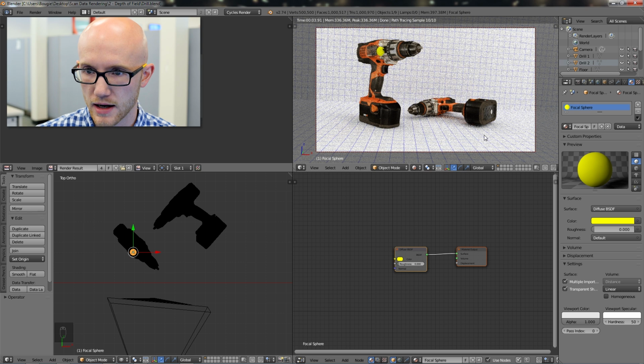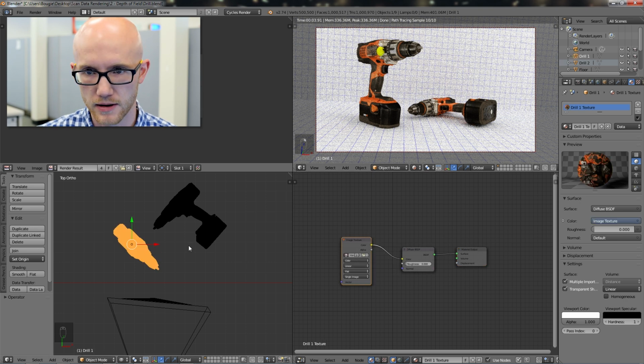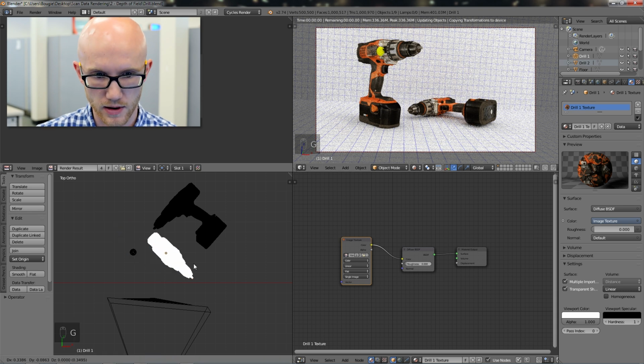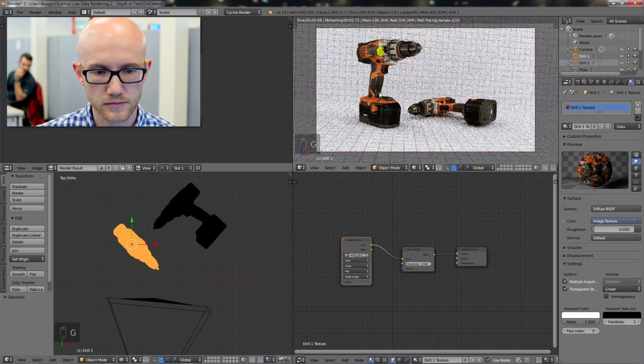And then this time, I've got my two models. I have textured planes. I added a grid that I created in Adobe Illustrator, and then exported it and tiled it to make it look real nice, give it kind of that mechanical grid type look. And then I have this yellow sphere here. This is the focal sphere. I've set Blender to focus on this particular sphere, but when you render the image, it does not show up in the final results. So wherever we put this is where the camera will be focused.